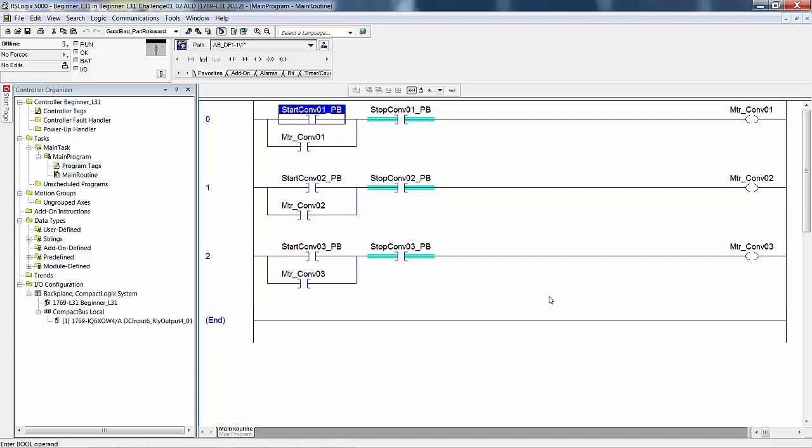Now, once you become confident in what you're doing, you can double-click on the tag name, edit the characters, press enter. Right-click on the undefined tag name, select new, and after making sure the tag scope is correct on the first line, then select create. This can be done in seconds, but only if you are confident in what you are doing.